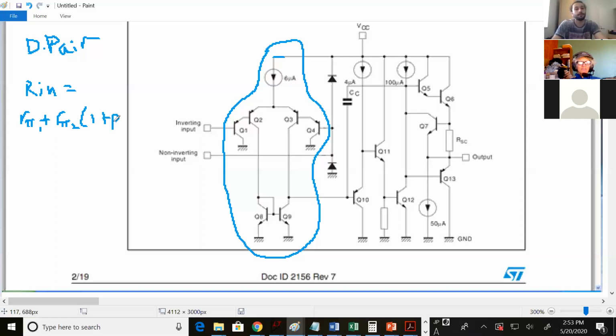So Q1 has a resistance it sees on its emitter, and that's just the input resistance of Q2. So the input resistance of Q2 is acting like that RE that you see with degenerated transistors. Usually in your equation you see an RE here, but in this case it's the input resistance to Q2, which is the resistance on the emitter, not a resistor of size RE. Okay, so that's super gigantic RN. That's exactly what you want for your input stage. While we're here, we have 7 minutes.